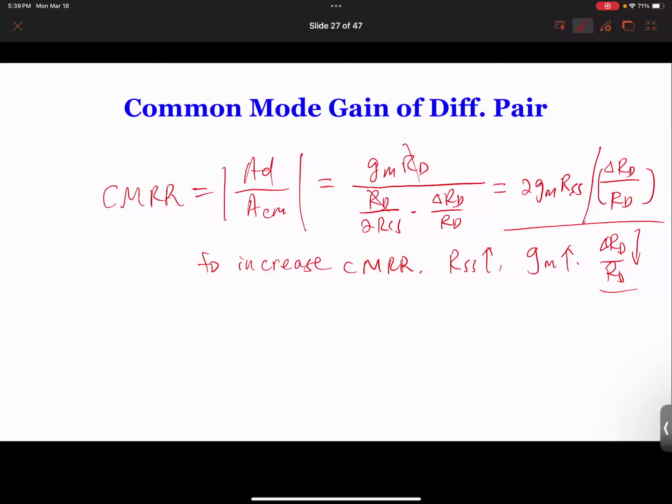In the common mode rejection section, we also talk about what happens if there is actually a difference. You can design for DC offset. Remember, we try to design the circuit so that it compensates for your parameter differences. That's why a good electronics designer can use cheap components but still design a good amplifier.